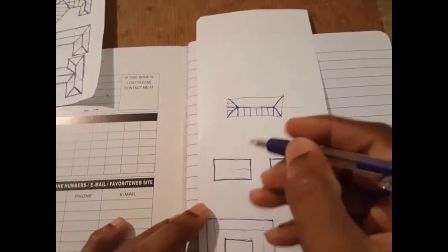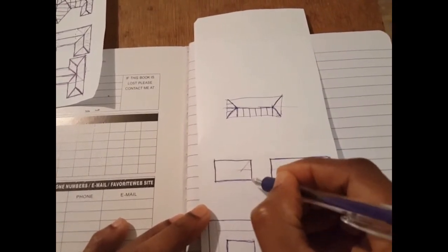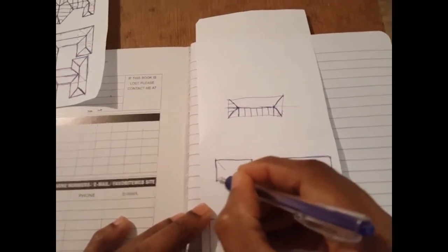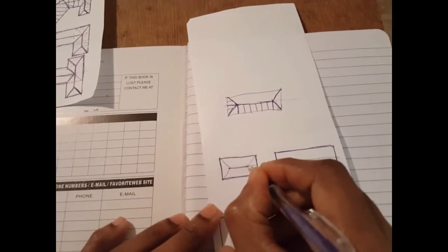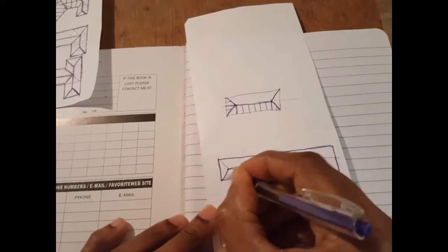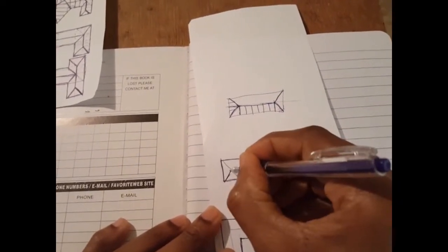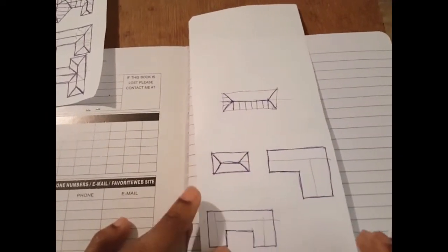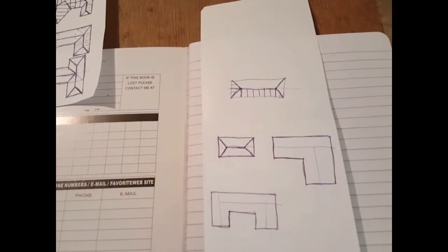So the first rule says that this must be drawn at 45 degrees. That's at 45 degrees. This is at 45 degrees. This is at 45 degrees. That's at 45 degrees. At the point where both of them meet, that section becomes our ridge. So we would brighten up all of that to get the roof outline. All right. Next, onto this one. Again, same principle applies.